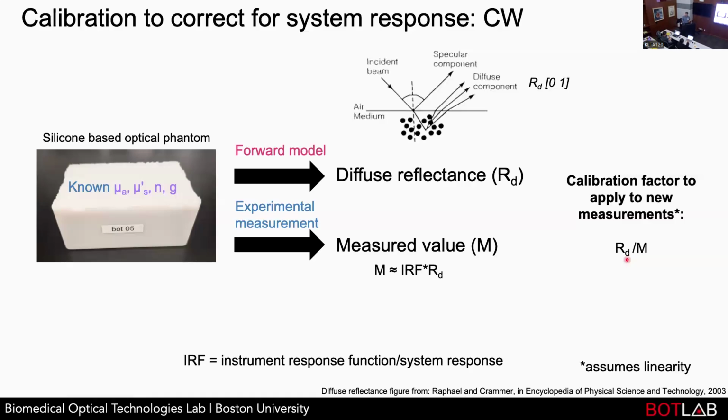How sensitive is your detector to thermal changes, and are you controlling the temperature inside the box? Thermal variations can affect your response quite a bit. We've dealt with that a lot, especially for the time frequency domain measurement I'll show you later, where we're running an avalanche photodiode at high voltages. It's a long-winded answer.